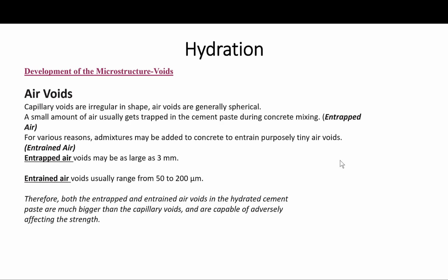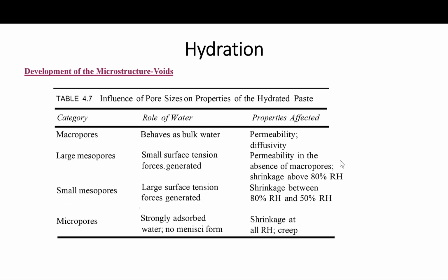So as can be seen from what's shown on this table here, porosity over the whole size range of pores has an influence on the paste properties. Yet, as I said, it is difficult to get an exact assessment of the pore size distribution, because no one measurement encompasses the whole size range, and because it is difficult to interpret experimental data. So, comparison of porosity should be made with care.